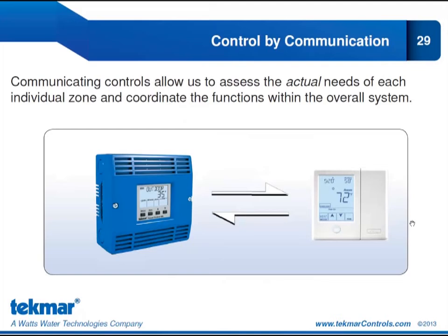So this is a very important consideration for a geothermal system design. How do we know it's time to switch the system from heating to cooling and vice versa? How do we prevent zones from trying to heat while the tank is filled with chilled water? These are all considerations that are addressed with communication. So over the next few slides, we're going to focus on how communication will help us to further reduce system water temperatures and further prevent equipment short cycling.